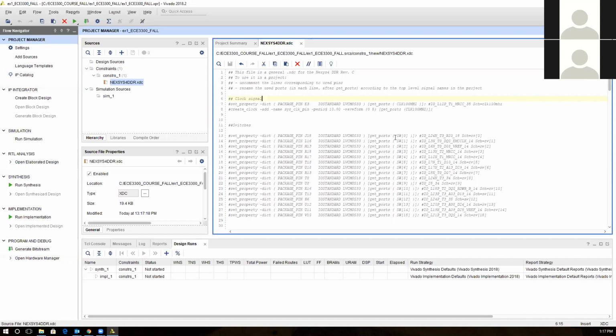So first of all, you have here the name and all of this, but then there's something in front of you called clock signal. There is a crystal inside the chip which is used for what? Generating the clock. To generate the clock, you have to uncomment these 2 lines, and the clock name will be here, clock 100 megahertz. So the maximum frequency out of this is 100 megahertz. We're not going to use it now, I'm just telling you.